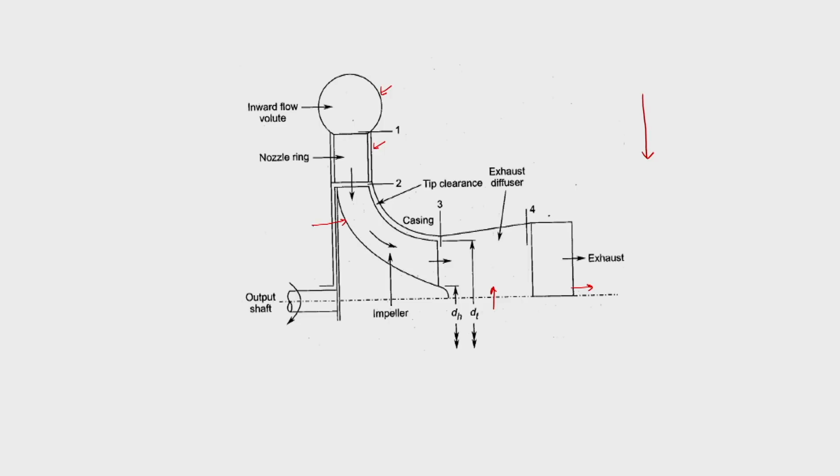The parts which had certain functions in the centrifugal compressor have the inverse function in the radial flow turbine. Here initially we have the nozzle, which were diffuser vanes in the centrifugal compressor. The nozzle converts the high pressure to the necessary kinetic energy: the flow at high pressure at the entry to the nozzle turns into high velocity at the exit.